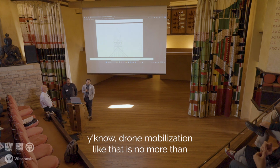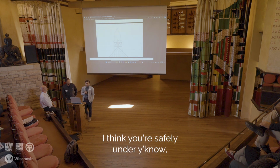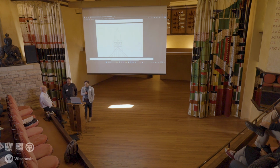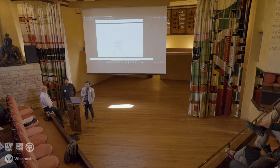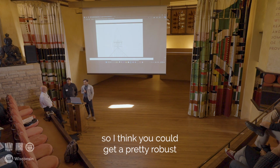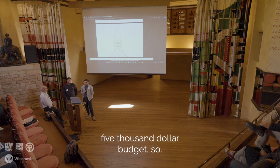A drone mobilization like that is no more than a half day in the field, and with all the post-processing, I think you're safely under a $5,000 budget. While you're out there, you're not scanning the entirety of it, but you can route your drone documentation to take one to two scans, which doesn't drive up your scan time in the field much. So I think you could get a pretty robust preservation set for a facade like that, in a half day, for less than $5,000.